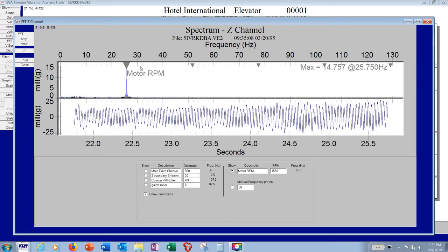And you'll see how it matches pretty precisely. So what it's saying is that the gearbox is actually the vibration source of this signal, because it's tied directly to the motor RPM. There is a match. So when you're using the FFT, you're looking for matches.